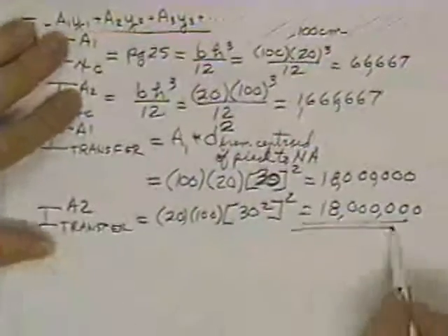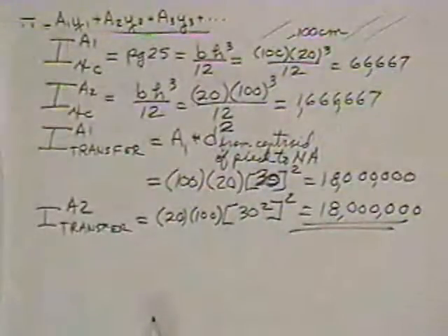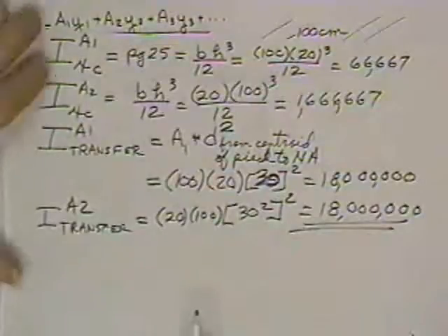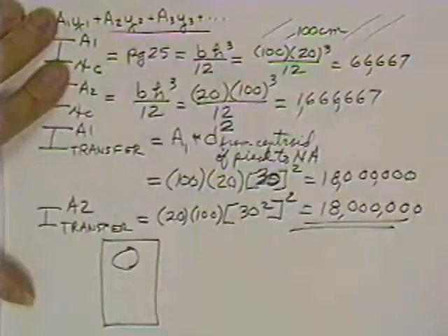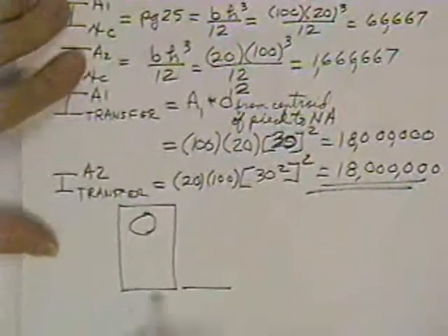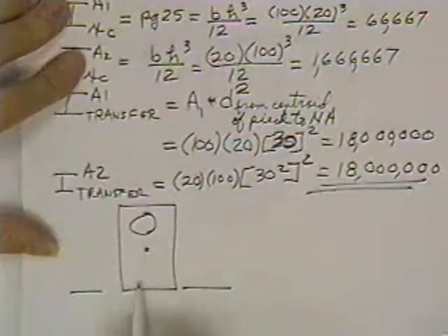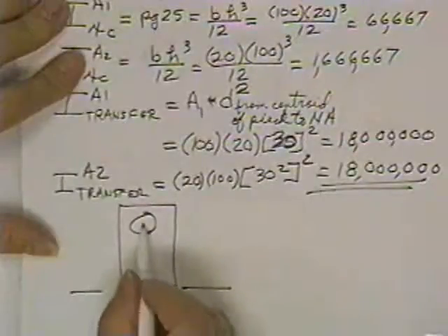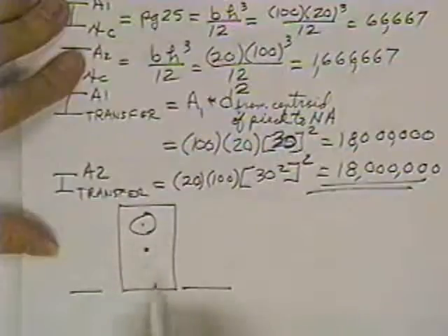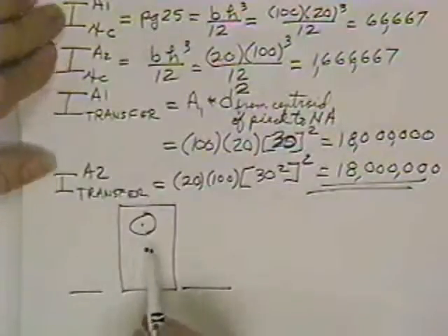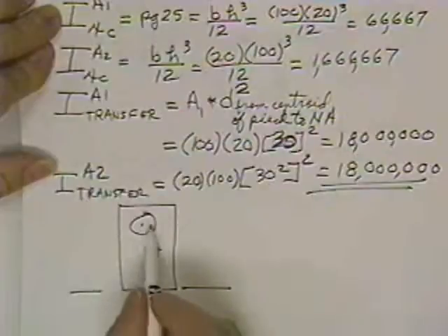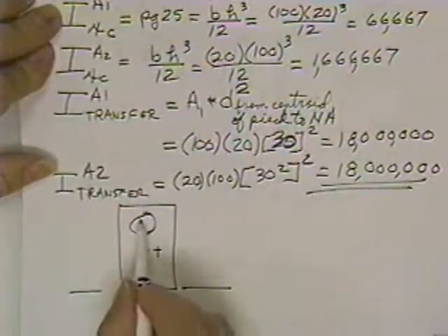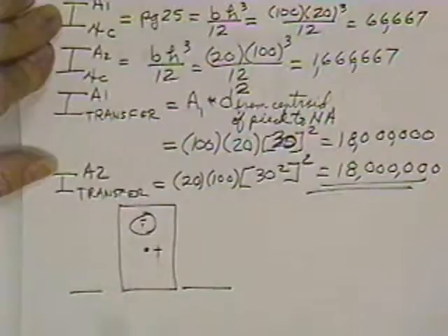All right. And then all you do is add them all up. They'll always be positive unless the area is a hole, like a missing piece. So if somebody gave you this, you would draw a reference axis, take area 1 as a positive area, then take this hole as a minus area, and solve for where the centroid is. When you did the moments of inertia of each piece by itself, this would be a positive area, and therefore a positive moment of inertia. This one would contribute a negative.